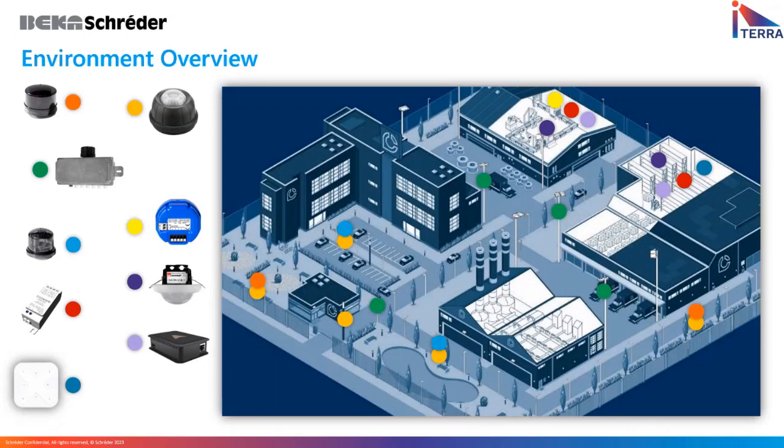What we have here as hardware is something very specific to our portfolio, but we are capable of incorporating almost anything nowadays that speaks on the DALI or 0 to 10 volt protocol. I have to mention 0 to 10 volt because we cannot broadcast, as it's not a digital input. We do not broadcast, so it becomes a one-on-one connection with a controller. But our nodes are certainly capable of also using 0 to 10 volt as a dimming state.